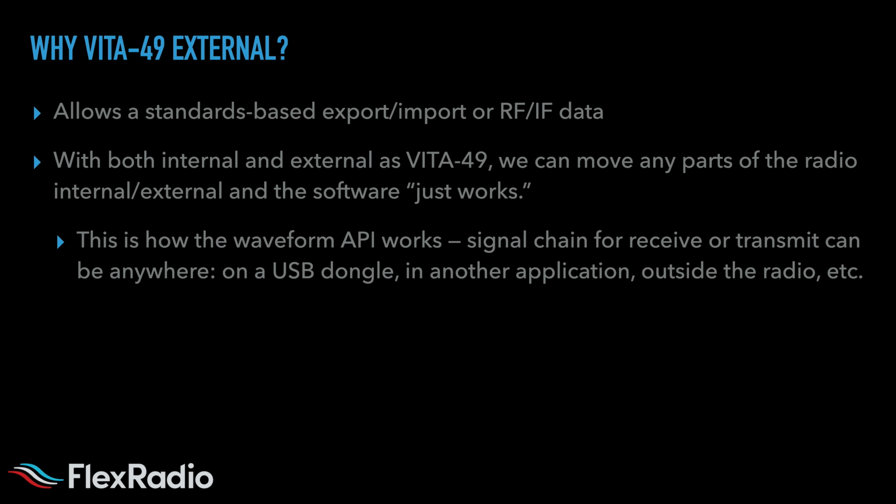So why do we use VITA-49 to go from the radio to our client programs and that sort of thing? Since we're under control of both the radio and our client programs, we don't have to go use a standard. But by using a standard, it allows anybody to connect to our radios and not use our client if they want, to create a new client using standard interfaces, any of those kind of things. And also because everything in our ecosystem, from the insides of our radio to the clients on the outside, use VITA-49, we can mix and match and swap any of those pieces and move them around, and everything just works.